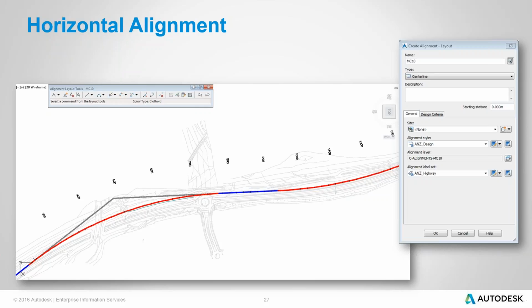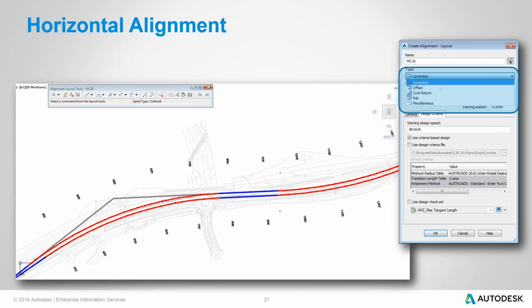The standard AutoCAD Offset command allows you to set out our construction lines from Civil 3D alignments. In this example above, the northbound alignment was initially set out. The construction lines were offset from the Civil 3D alignment using standard AutoCAD Offset commands. This has provided guidelines for the setting out of the southbound carriageway control. We then complete the design layout by creating the side road alignments connecting to the through road alignments.